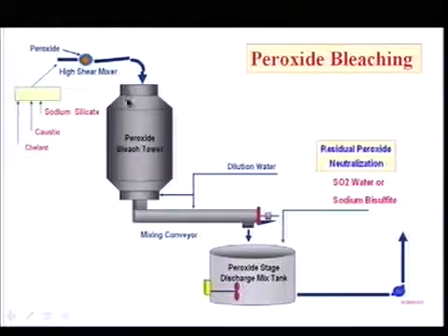The chemicals are intact with the fiber. It goes to the bottom. You are putting it in at a consistency of 30-35%. Here white water is added to dilute to 10% consistency, and the fiber is conveyed in this conveyor at 10 to 12% consistency. More white water is added to drop the consistency to 5% into this tank.